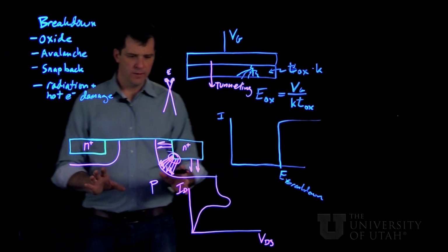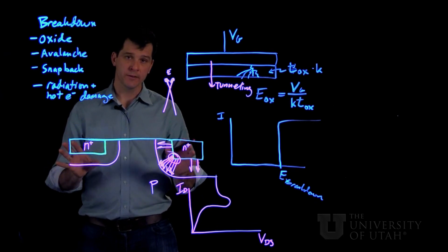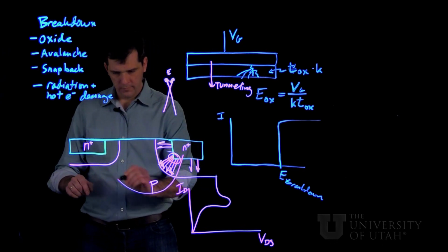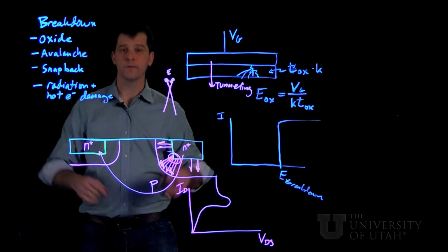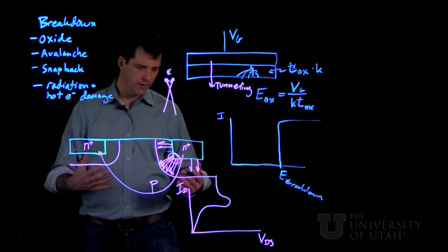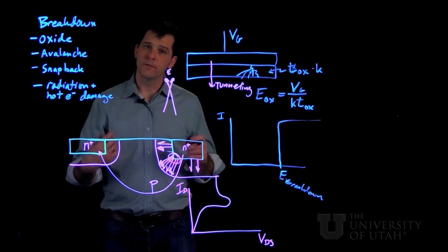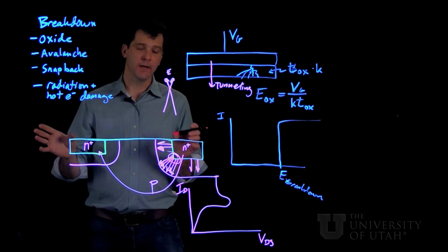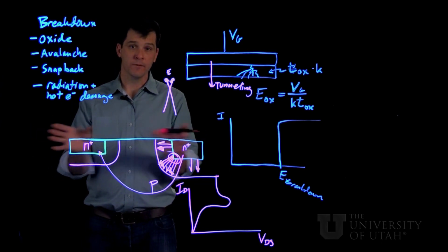And this is because the MOSFET can actually be considered to have a parasitic bipolar junction transistor that runs in a path like this. So if we look at this path, it's NPN, which equals a bipolar transistor. And bipolar transistors are known to have this high current, low voltage state. So this is also related to the phenomenon called latch-up when you're looking at a CMOS structure having a P-body and N-body MOSFET next to each other in your logic circuit.